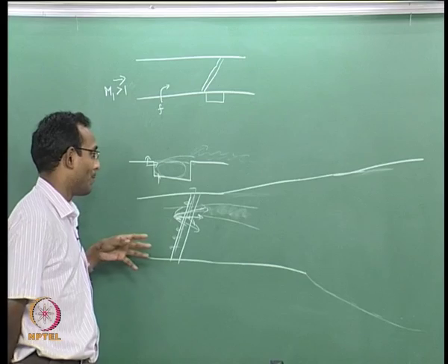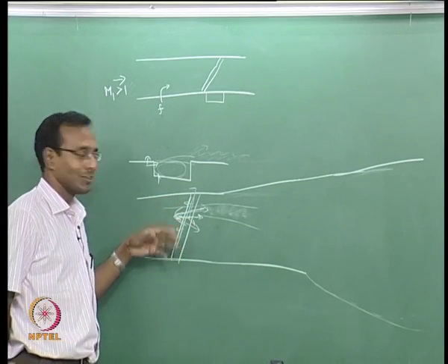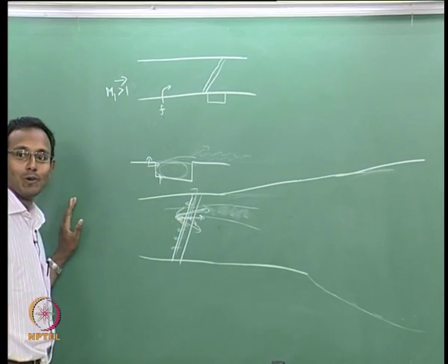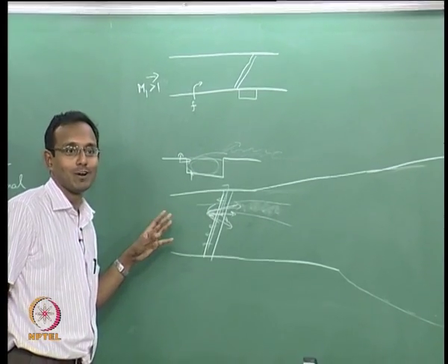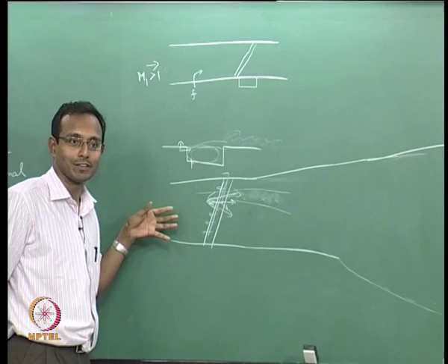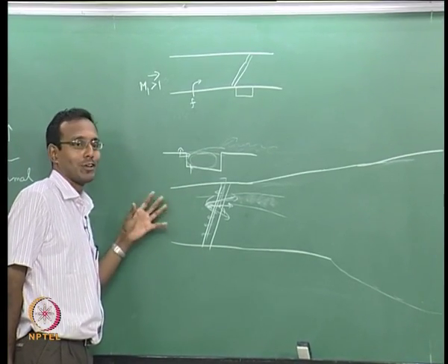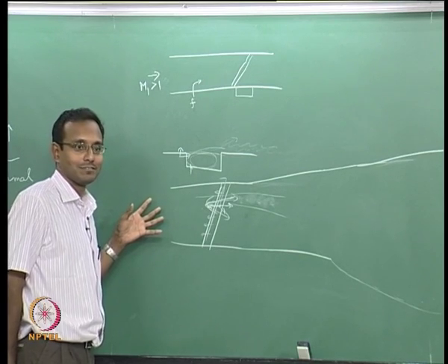And by mistake, if you added a little extra fuel than the choking limit, the whole flow chokes, there will be a shock running straight ahead, and the whole flow becomes unstarted. The combustor is called unstarted. What happens is the incoming flow will become subsonic. It jumps and takes a subsonic solution, it is no more a supersonic combustor, it is burning subsonic. So they call it unstarted condition.